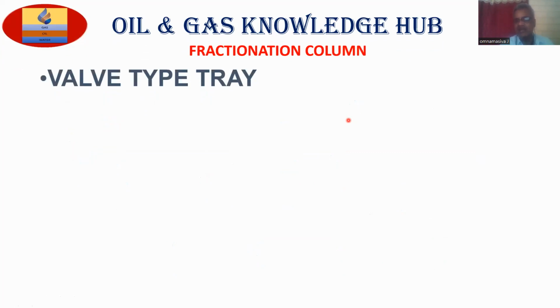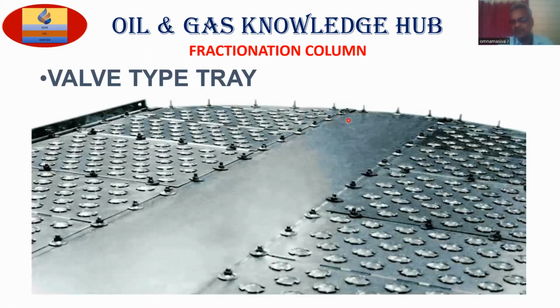This is the third, valve type trays. These are valve type trays. The function remains the same. This is the weir plate. From the weir, it will go to the downcomer. Same thing. Okay. Depending on temperatures, they produce different products, and these will be transferred to the respective product columns via pipe. Like this, you can see.